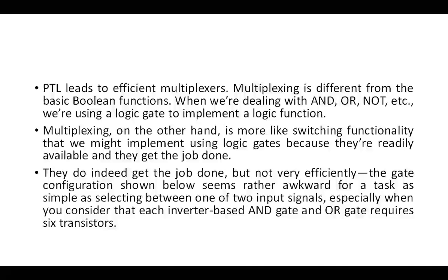And once I have the MUX, I can implement any function, and these are readily available, which means they are manufactured, and I don't have to combine AND gate, OR gate, make a complex circuit, connect wires between them. No, I can just use a MUX, and using MUX I can program it and make it work like any other logical circuit.